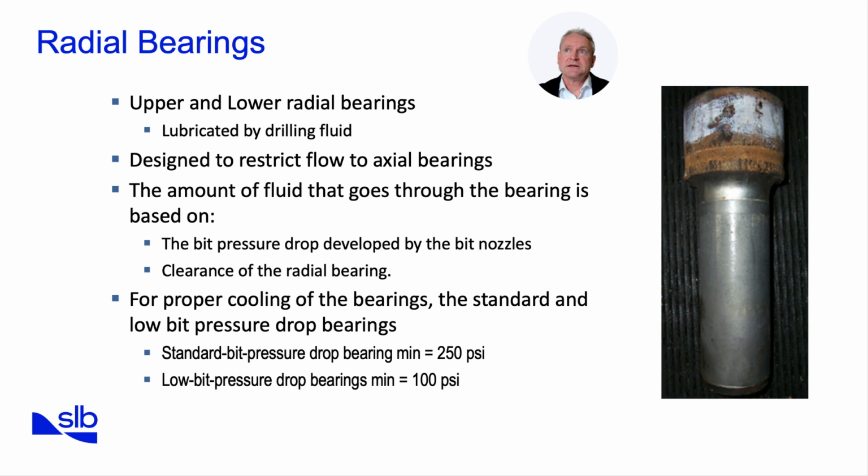Radial bearings are designed to stabilize the motor shaft and resist side loads encountered during drilling. They are lubricated by drilling fluid which flows through small clearances, cooling the bearing surfaces and limiting friction. Proper flow regulation is essential, since inadequate lubrication can quickly lead to overheating and failure.